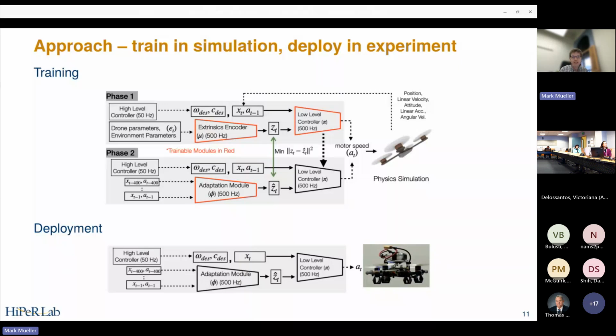So this feels a little bit like indirect adaptive control, right? You can sort of imagine you have the adaptation module that serves the role of something like your Kalman filter might have served. This then generates a state estimate that you then parameterize, maybe an LQR that's parameterized in the estimate from the Kalman filter. The architecture is familiar in that sense, but important to note is that this is all without us specifying what the estimate should be, right?